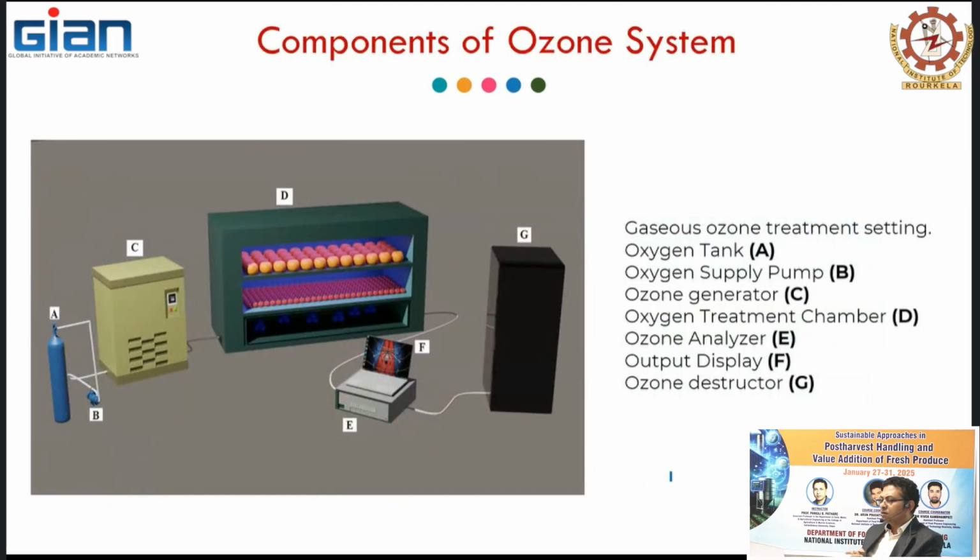So it's just like a simple process. Maybe we have the commercial one generating the ozone, setting one. Now here, from the oxygen tanks, or sometimes maybe directly from the air. If it's oxygen tanks, maybe you are getting the pure oxygen, so you get the ozone. Otherwise, you have the oxygen air, where we need to dry it up in the system to pass into the generator.